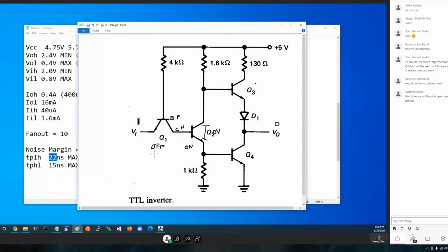Well, I'm guessing because it's grounded, Q3 would be off. Well, we have ground here. Now, let's think about that a second. It's not exactly grounded. If you look at this transistor right here, which we know has to be on, we know that has to be on, and we know this one has to be off, but let's justify it. Because that's the opposite of what it was in the last picture.